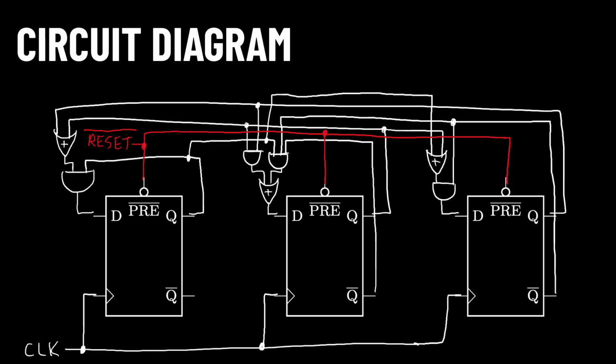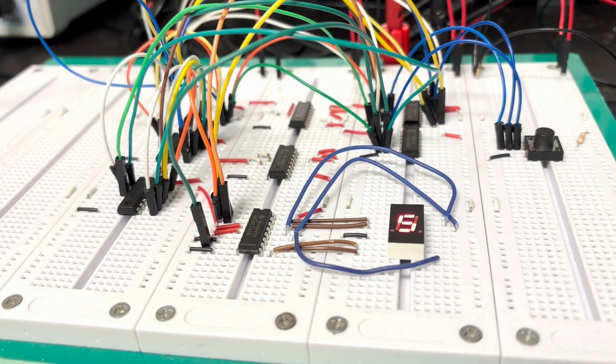The circuit diagram is generated the same as the other sequential circuits we've seen so far. Connect the clock input to a common clock signal, then wire up the input values. Once the flip-flops complete their countdown, the output will remain at 0 indefinitely. What if we want to watch the cycle again? We can asynchronously set each flip-flop, giving each output a value of 1.